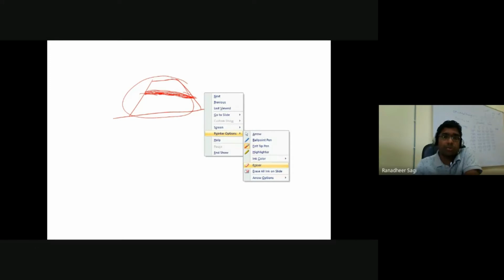In order to take care of all these issues, let's say I have this earthen embankment in which the flow through it is expected to cause a failure on the downstream region. What I can do is provide some kind of drainage path.